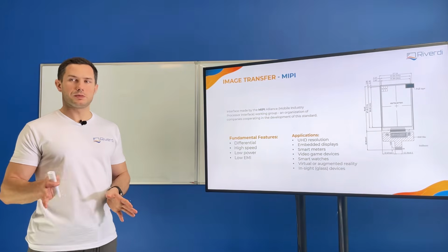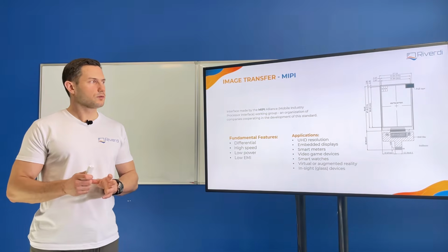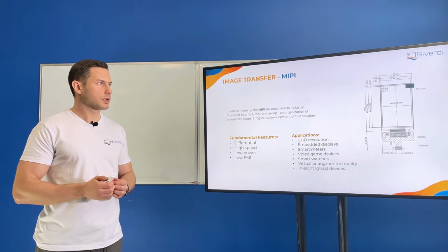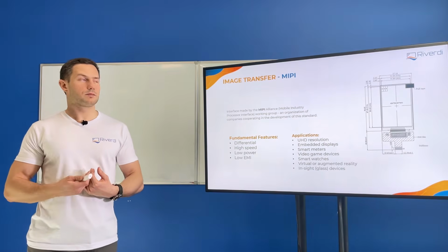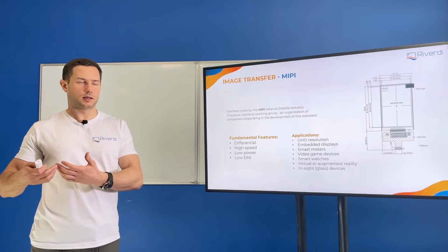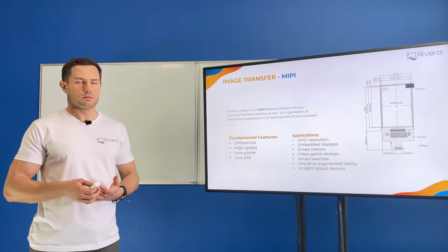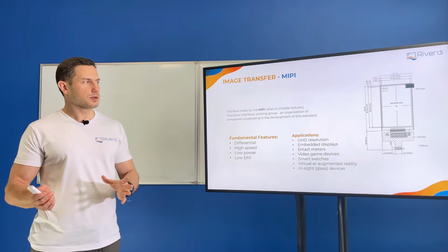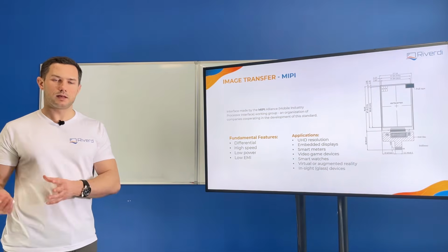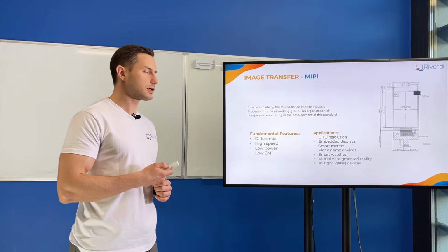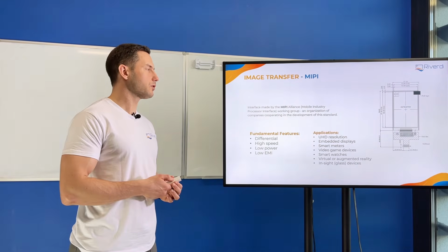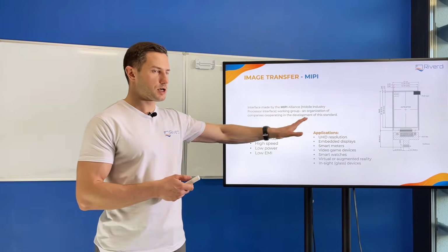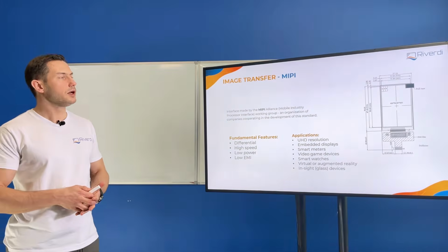But be careful with the MIPI displays on the market, because many of them come from the mobile phone or tablet market, and then the availability of the TFT glass may not be stable. So please double check what you are buying, because the display with MIPI that you buy nowadays may be phased out pretty soon, when the mobile phone built on it is phased out as well. This market changes really fast, every 6 months or every year.